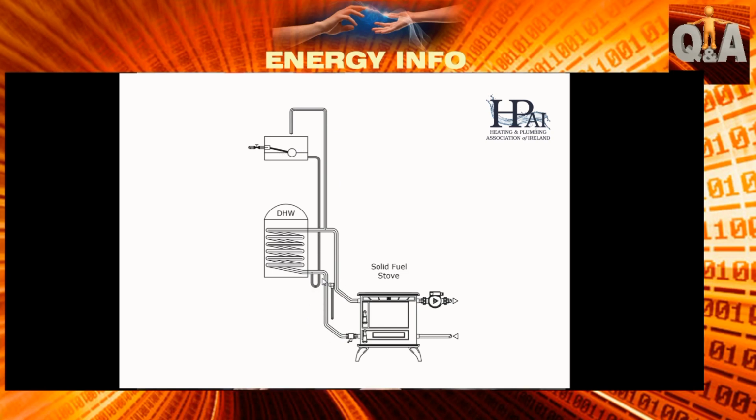So you have a perfect reason for the hot water, having been heated by the fuel, to rise, be cooled by the water, and fall back down. In the meantime you have an open expansion and you have a cold feed. So that's the standard, very natural way for a thermosiphon to work. On the other side, if you're pumping from the other side of the stove, you have full pressure leaving on the pump, heading out to your radiators or whatever system you have, and coming back again to your neutral point. Again, a very good system, a 4-pipe system.